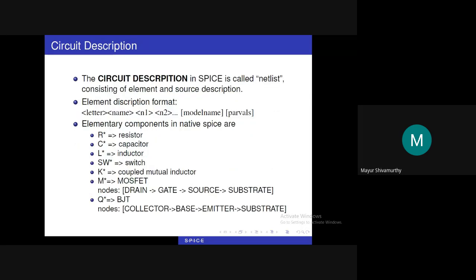So let us come to the circuit description. The circuit description in SPICE is called a netlist, which consists of element and source descriptions. Any element description is in the form of a letter followed by a name, then the different nodes associated with it, and model names and parameter values. For example, the resistor is defined by R, so it can be R1, R2. Capacitor is C, inductor is L, switch is SW, K is for coupled inductors.